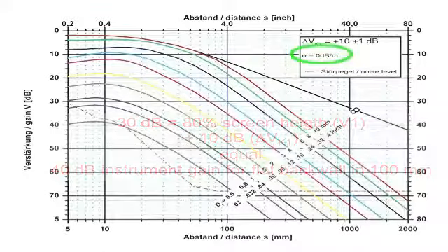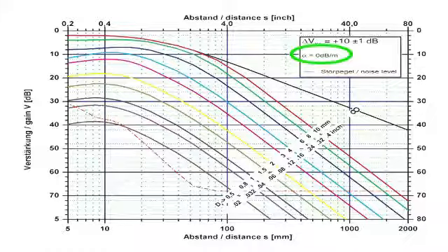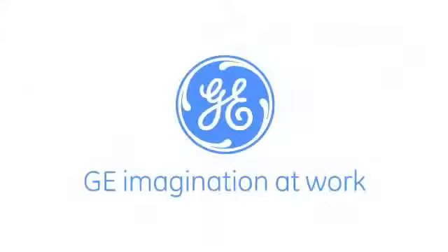One last comment regarding sound attenuation. On each of GE Sensing and Inspection Technologies' DGS diagrams, the remark alpha equals 0 dB per meter can be found. This means that the given diagram is only valid for attenuation-free test materials. Since this is an ideal assumption, the user is obliged to know the specific sound attenuation of the material they are testing, and must correct all echo amplitudes if their material attenuation is not negligibly small. We'll help you get it right.